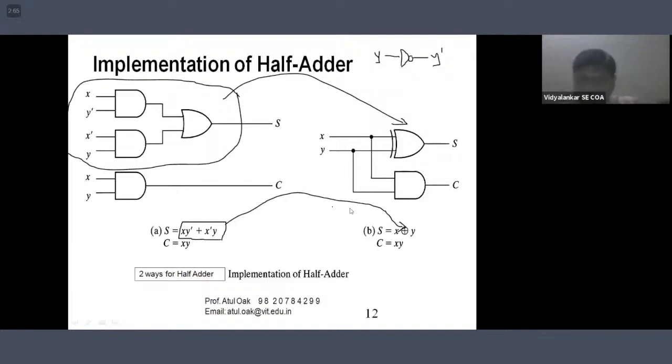Okay, what is the plus and what is the minus? इसका प्लस पॉइंट ये है कि you are realizing this entire hardware using only basic gates: AND, OR, NOT. These three gates are basic gates. Okay, and availability of basic gates is better than availability of other gates. इसका ड्रॉबैक ये है कि इसमें नंबर ऑफ गेट्स इंक्रीज होते हैं.